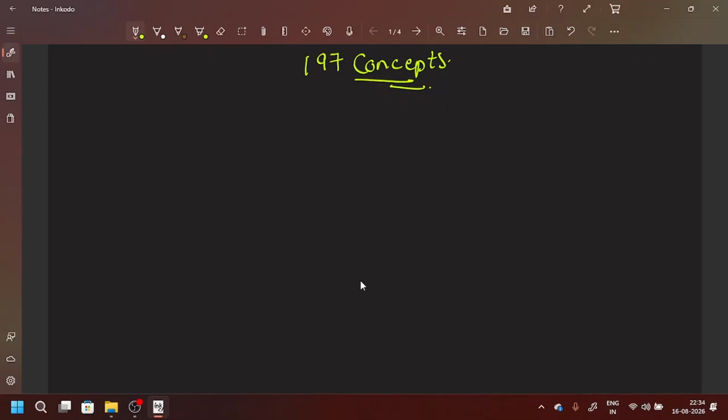So if you just look at the circuit diagram, I'm going to take an op amp. Definitely we will be using its power supplies, so this is minus VCC and this is plus VCC. Then we have the inverting input and non-inverting input. The non-inverting input is connected to ground, and this inverting input is connected to the output via a feedback resistor.